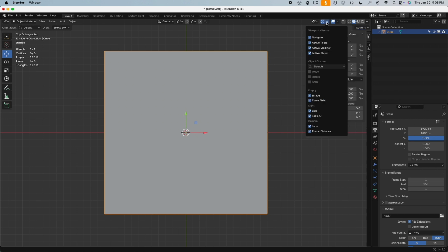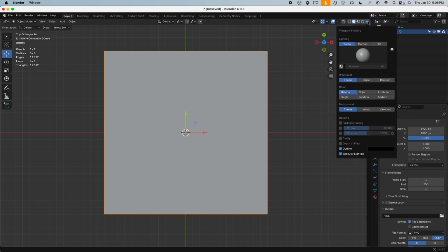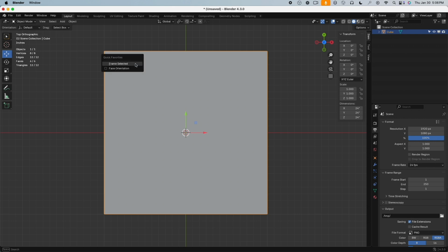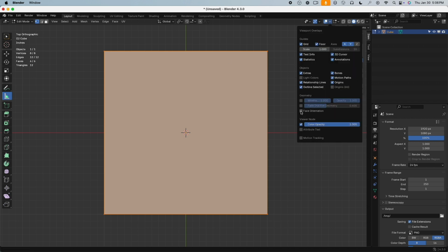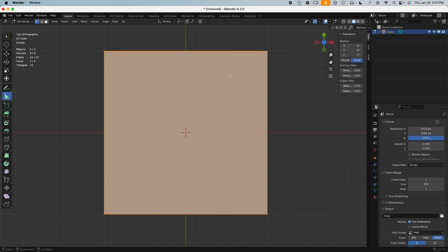And where was the mesh stuff? No. Oh, this is in edit mode. So if I press Q, you see now face orientation and edit mode Q. It's not there yet. Right click and add. And then, yeah, here it is. So edge length, right click and add. Because then if I press Q now, you see it calculates the edges for me. I don't have to measure it, it does it automatically.